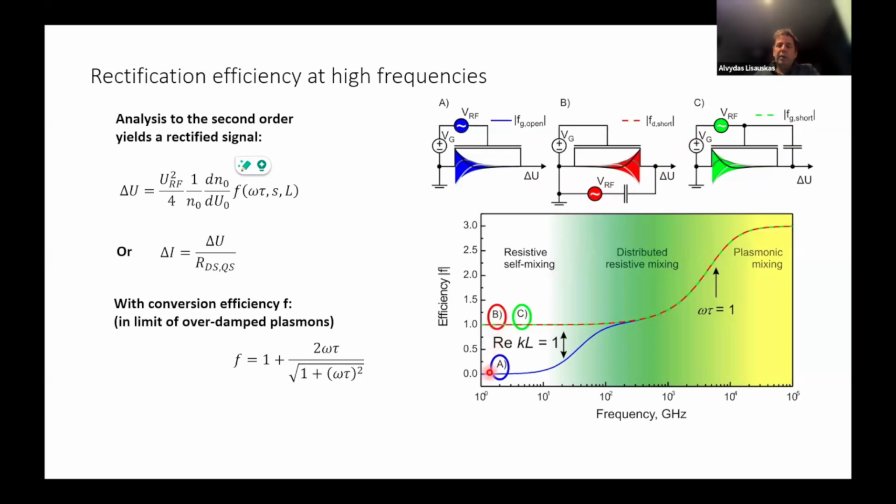Those are 3 scenarios. First of all, the scenario of Dyakonov and Shur showed here that there will be no rectified voltage, or this efficiency factor here, at low frequencies. And suddenly it would appear at very high frequencies, where the plasma waves start to form. This is close to the cutoff frequency, or KL equals the real part of KL(x1), where we have one wave entering the full length of the device. So for them, it appeared that this is really a high frequency phenomenon, but it is enough to look at it in a different way, just bias it slightly differently, to find out.